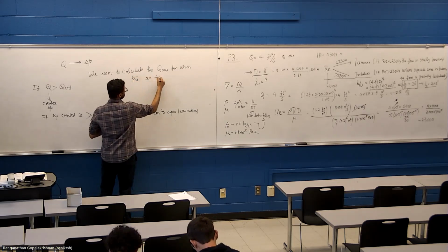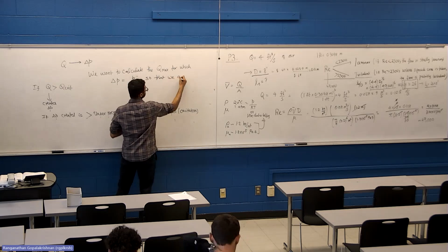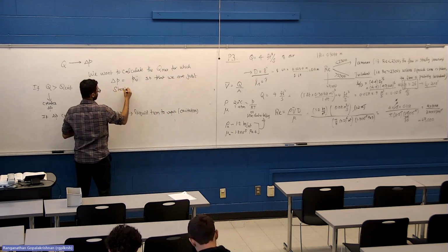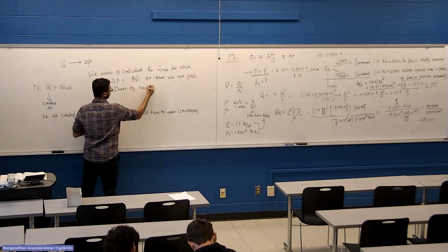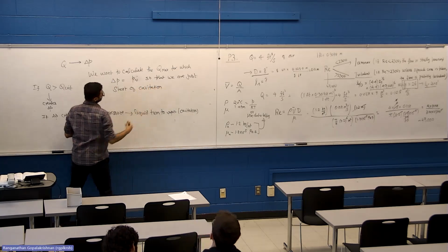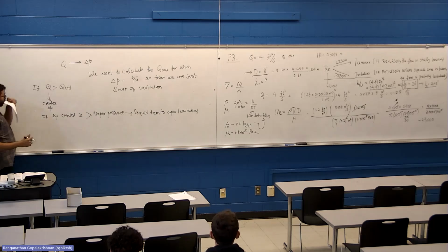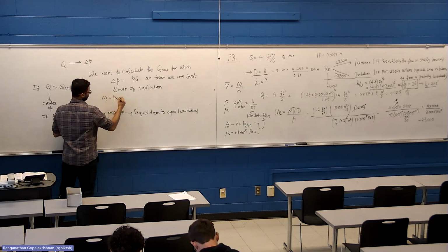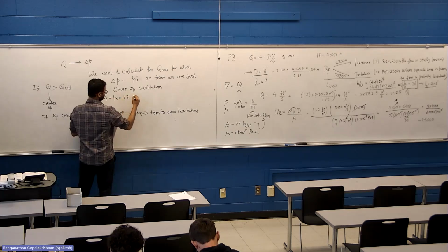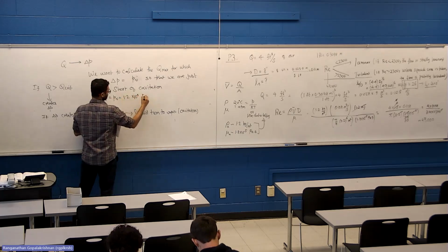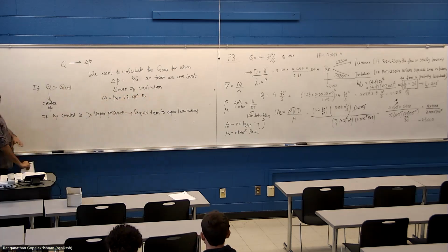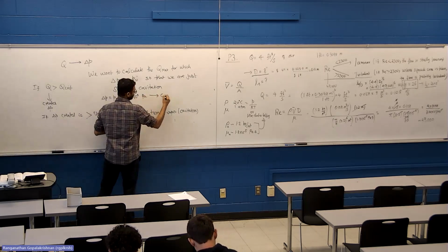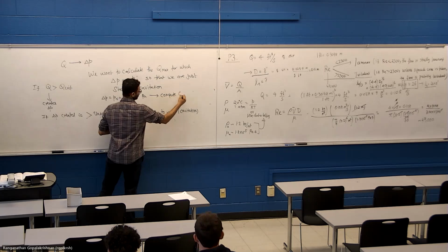so that we are just short of cavitation. Like calculating the maximum possible flow rate. So what you want to do is assume delta P equal to PV, which is given as 1.2 times 10 to the 4 pascals. And for this delta P, compute Q.